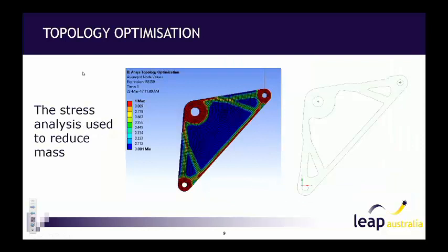So using this stress analysis, we can reduce the amount of weight. I know some of you have already done it, but the optimization algorithm first determines the material that can be removed, and it determines it by the input parameters, looking at the stress, displacement, and any other input variables. The program removes elements by effectively giving them a zero stiffness value and then rerunning the simulation.